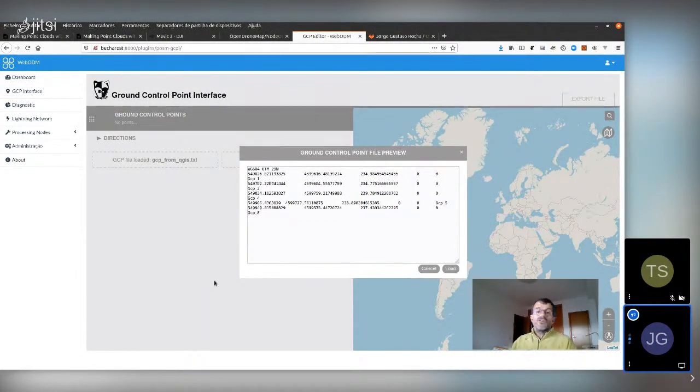So you have to create this kind of file. Usually I create this in QGIS. I grab the ground control points as a Geo Package and put them in QGIS, where I usually convert them to UTM coordinates. OpenDroneMap will not handle decimal degrees coordinates, so the first step is to find the UTM coordinates of the place. You try to see in which UTM zone, north or south, you are, and use that coordinate system.